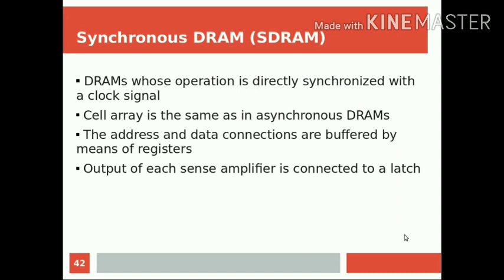In this video, we will explain synchronous DRAM. DRAMs whose operation is directly synchronized with a clock signal. That is a synchronous DRAM. The cell array is the same as in asynchronous DRAMs. The address and data connections are buffered by means of registers.